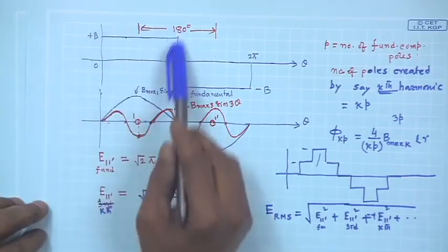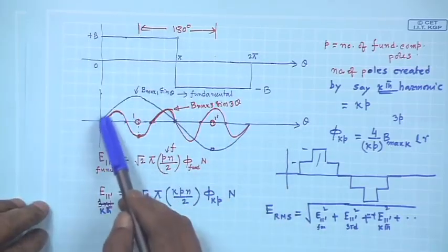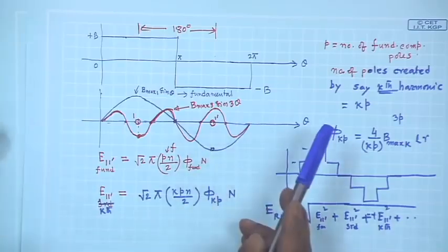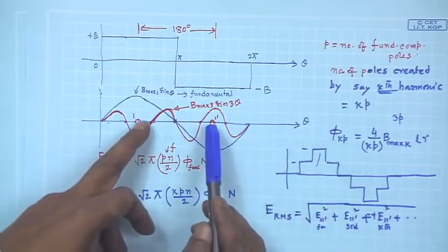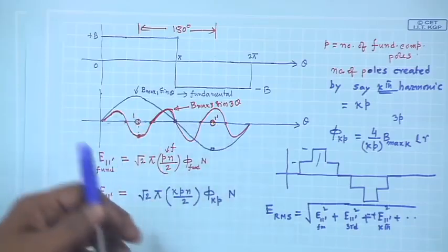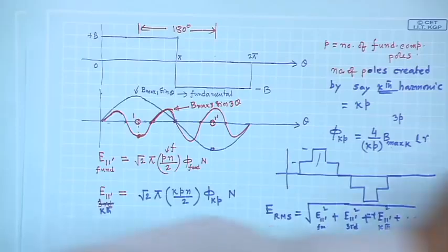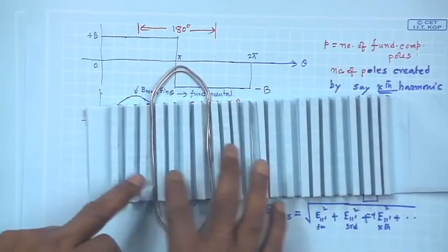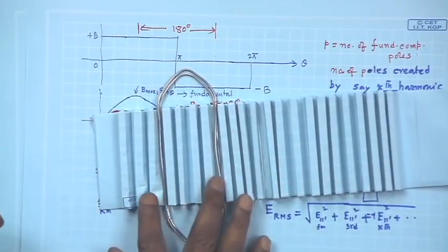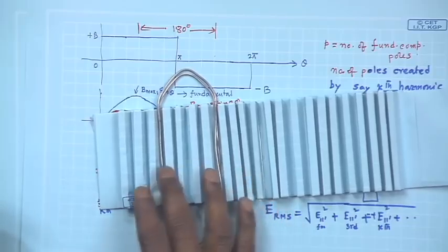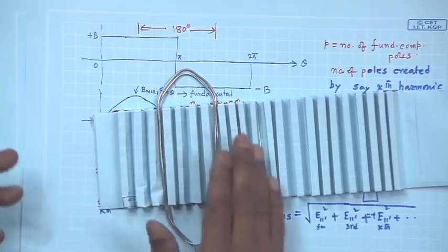So, I will do Fourier analysis, and this is, suppose, the fundamental component, and based on this fundamental component the coil span has already been fixed, and this I cannot change. I have fixed the coil sides into two identified slots where this angle is 180 degrees electrical. This I cannot do anything about, that is fixed.